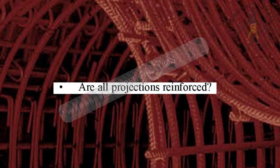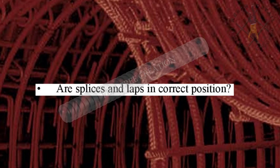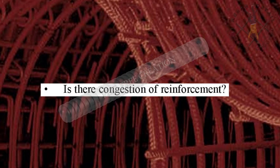Point 16, are all projections reinforced? Point 17, is the cover specified and correct? Point 18, are splices and laps in correct position? Point 19, do splices suit construction joints? Point 20, is there congestion of reinforcement?